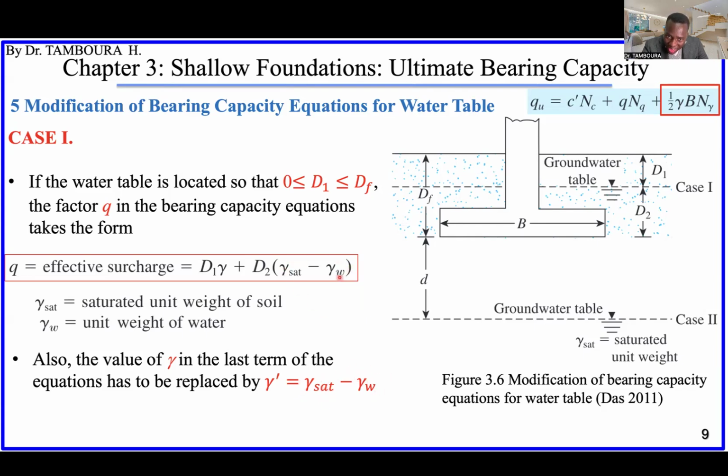As you can see, it's the same here, right? But this is supposing that the soil is uniform. The gamma sat of this place minus gamma w. So in this equation, you have to replace it by that. Is that clear for everyone? Sometimes, supposing that the gamma sat of the soil beneath this level is different, as I said, sometimes the soil here is different from the soil here.